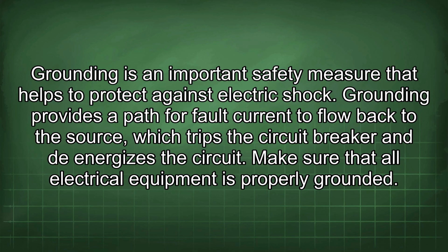Grounding is an important safety measure that helps to protect against electric shock. Grounding provides a path for fault current to flow back to the source, which trips the circuit breaker and de-energizes the circuit. Make sure that all electrical equipment is properly grounded.